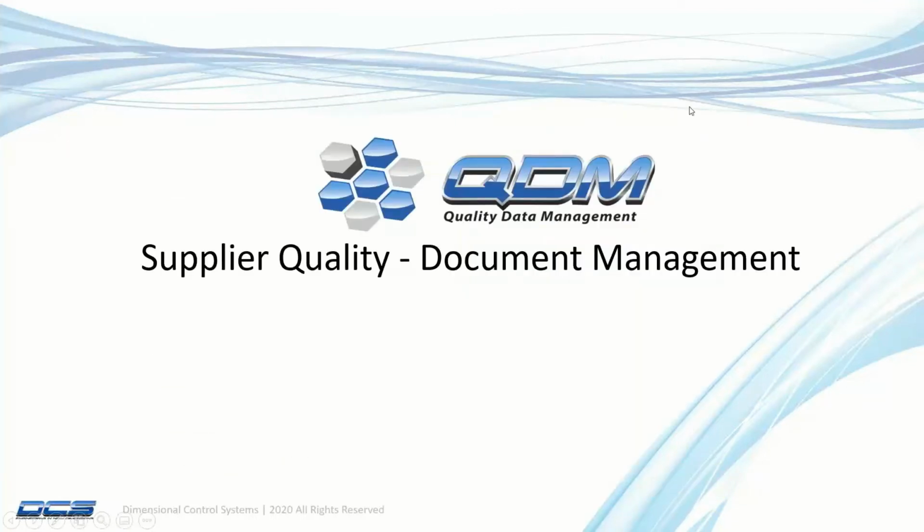All right, so now we move to, that's about data management, physical measurements. Now we talk about the need for documents. There are gate reviews, there are PPAP approvals. If you're in aerospace, then there's AS9102 first article inspection reports, gauge certifications, gauge R&Rs, and all those types of documents also need to be maintained for each inspection program.